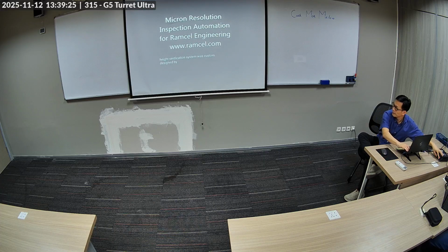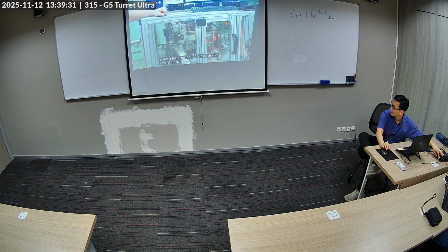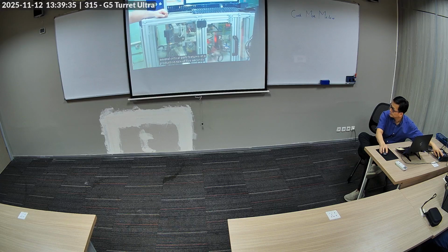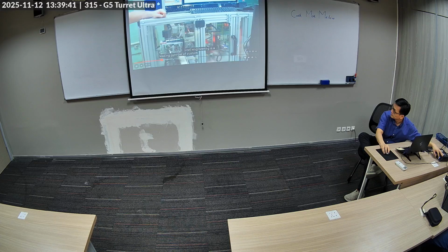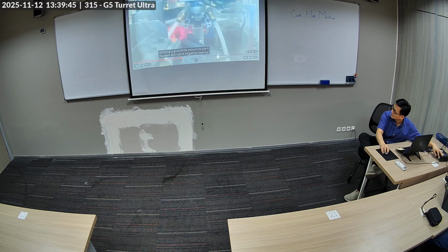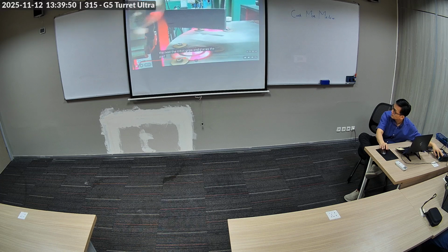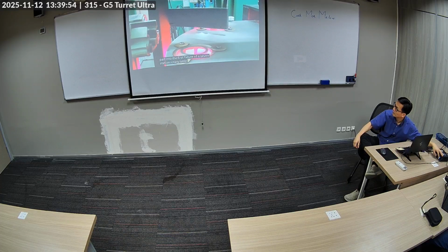It's custom designed by Compass Automation for an end user that required 100% inspection of several critical part features at a production rate of 5 seconds per part. The customer, Ramsell Engineering, is a leading provider of custom tooling. A 2-axis robot checks for part presence in the nest. The robot grips and places the part into the first fixture of a 7-station rotary table.